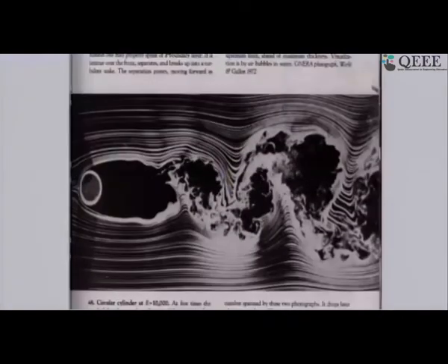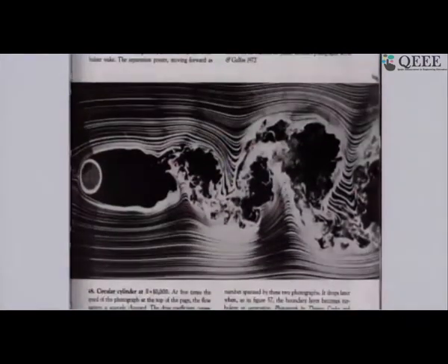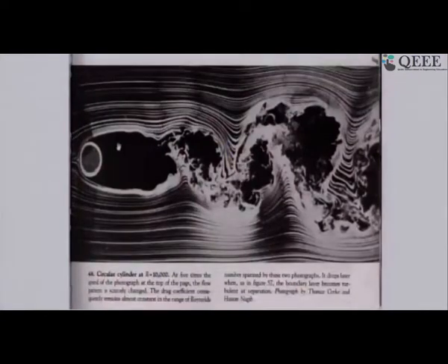And you go to even higher Reynolds number. This is now Reynolds number 10,000. What has been done is a layer of smoke has been put into airflow, and then you see where the streaks of smoke go. You see a very different type of pattern, where this fluid is coming in and bends in there and goes off. This fluid bends in here and comes out. Then this fluid is bending here, and after a while again this will come. So what you are seeing here is that alternately these vortices keep going off from this cylinder.